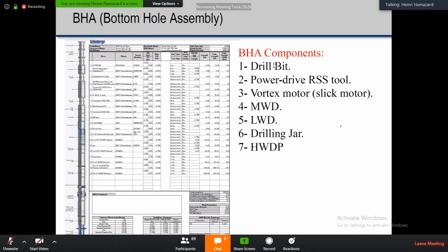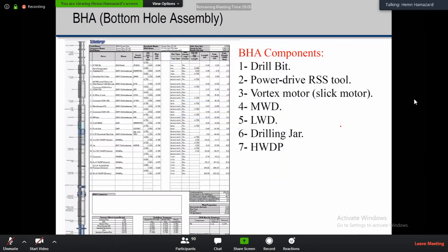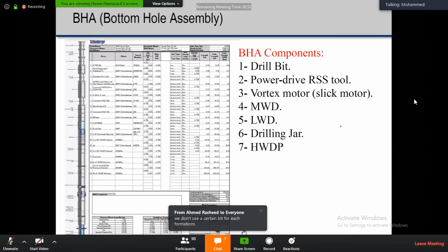Yes, there is no problem for casing. The casing is so flexible; it's much more flexible than the pipe. It can take the shape of the whole trajectory at any point, not even only at the deviated part. We use tubing, which is a smaller size of casing, even for 90 degrees. We've set tubing at 300 meters of the horizontal section. Can you imagine your hole is going like this, and the tubing is also going like this. So it's quite flexible to take the shape of the hole. Okay, no problem.